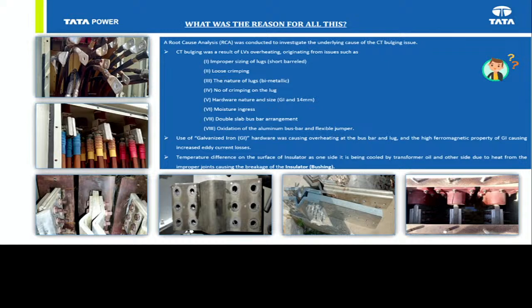Later on, when we replaced these GI nut bolts with SS, the temperature was lower. So one of the conclusions was that we replaced all cable set GI nut bolts with SS steel nut bolts. All these things we have explained, we will find in the next slides also.